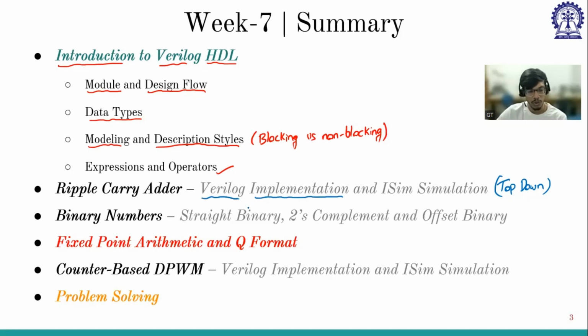Whenever we are going to write something, first we have to fix the architecture, say in terms of a block diagram or timing diagram, and only then should we start writing code so that we can debug easily. And then we check whether the code is right or wrong using the simulation.